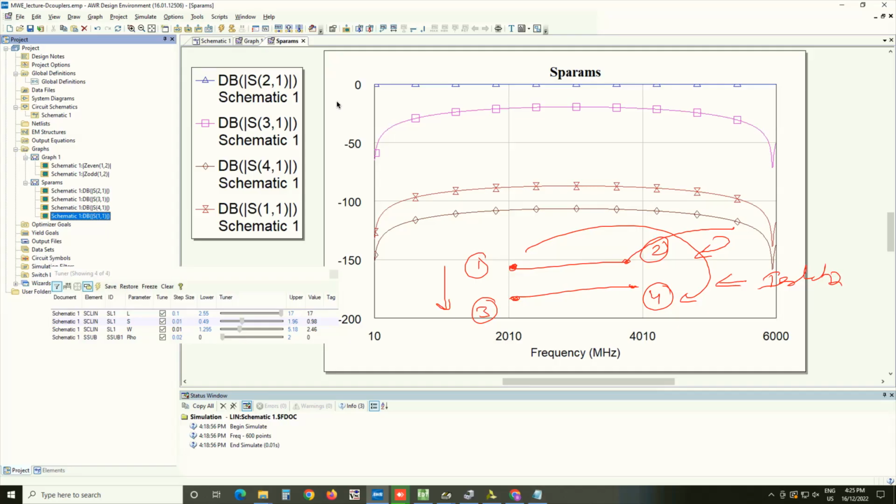That also makes sense because I can make the isolation larger by making the coupling weaker. But that doesn't help, because then even the wanted signal you are measuring goes down. So that's why it's the difference between the coupling and the isolation. So coupling is 20 dB, isolation is 40 dB, then directivity is 20 dB, the difference of 20 and 40.